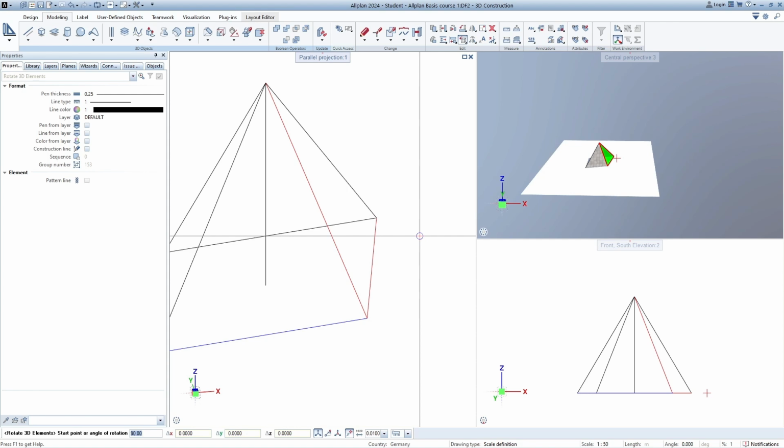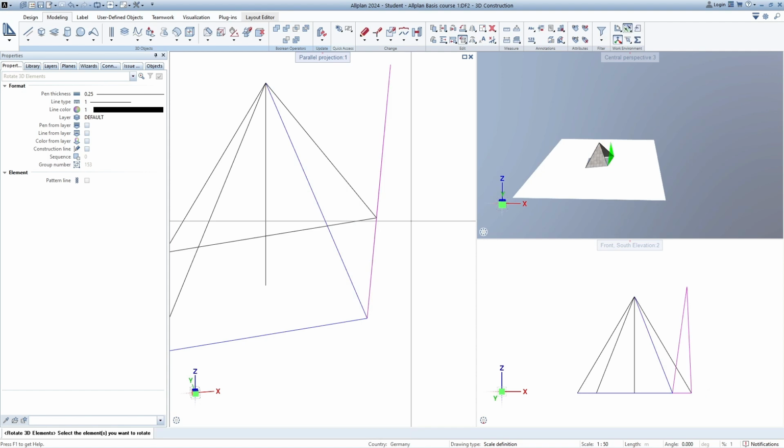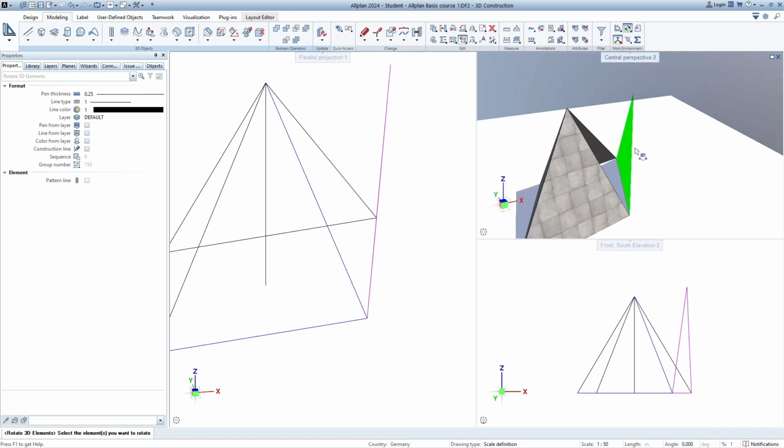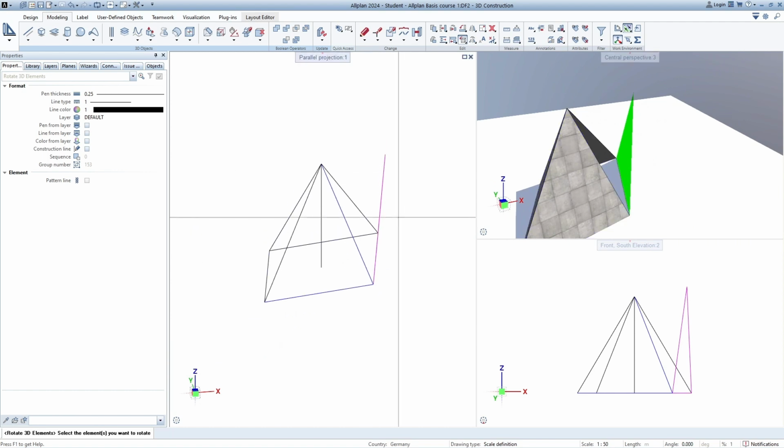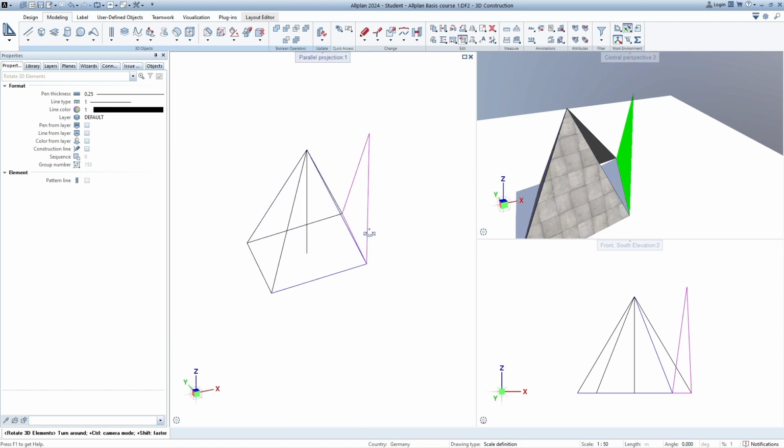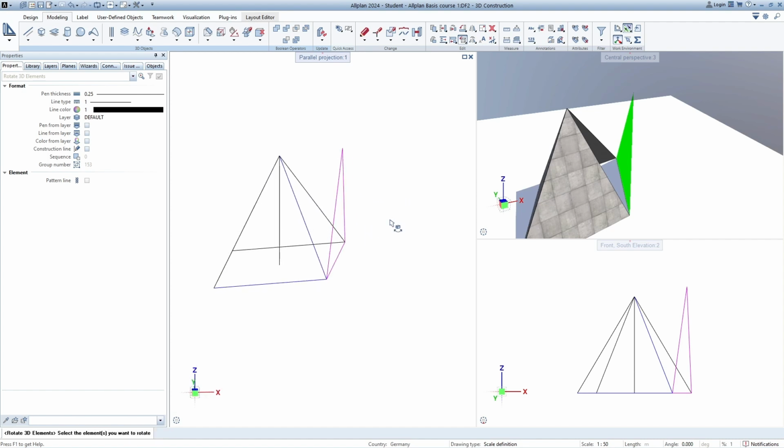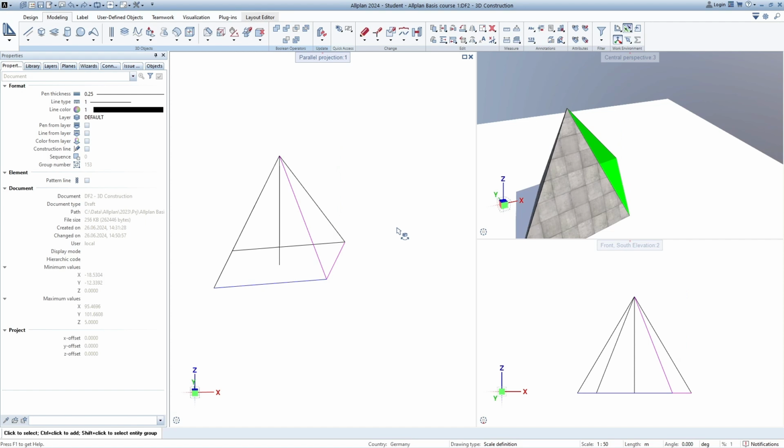And now we could go ahead, I just want to demonstrate it to you, and basically input angle of the rotation. So let's put, for example, 30 degrees, just like that. And there it is. Since we don't know exactly the angle of rotation that we need to basically put this 3D surface in our plan, we can just press Ctrl Z and just use a different function.